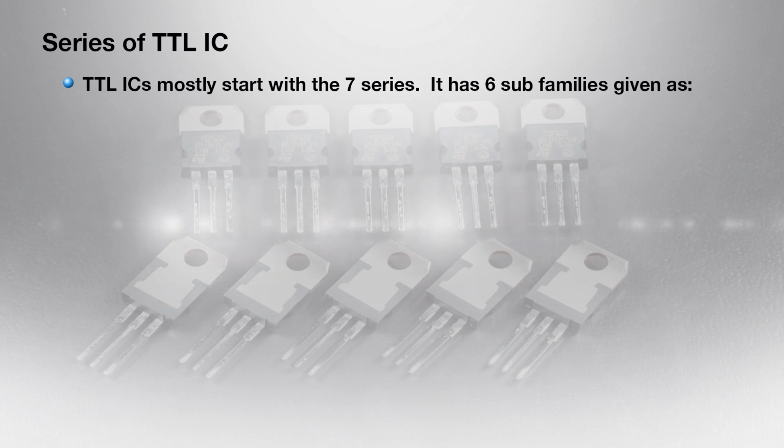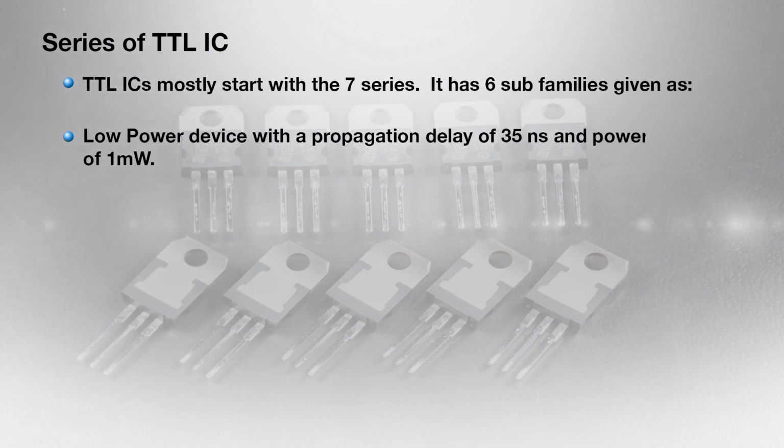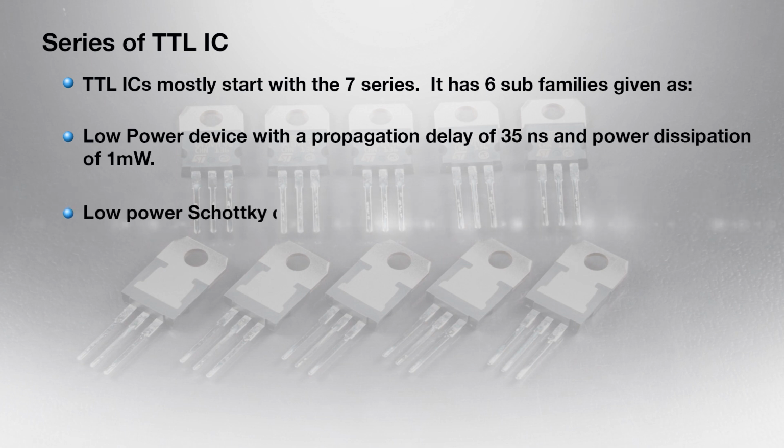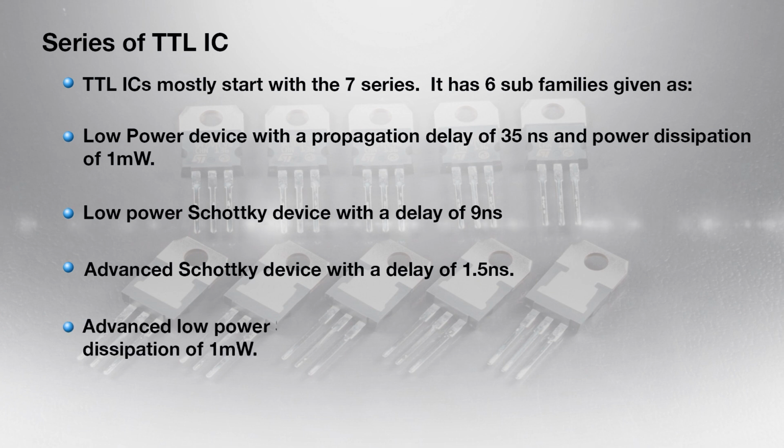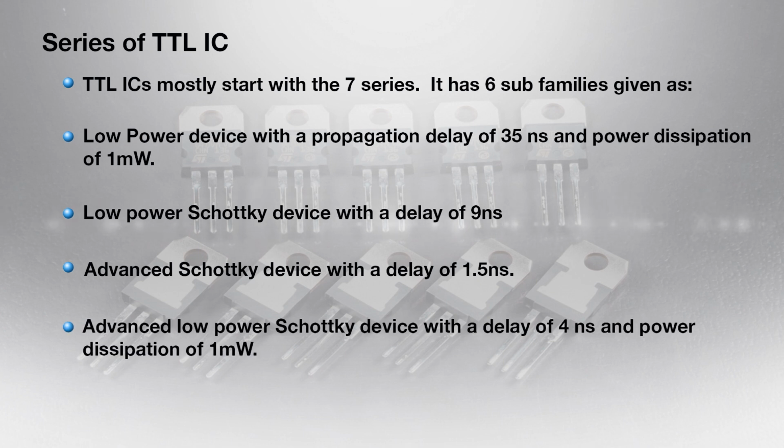It has subfamilies given as low power device with a propagation delay of 35 nanosecond and power dissipation of 1 milliwatt, low power Schottky device with a delay of 9 nanosecond, advanced Schottky device with a delay of 1.5 nanosecond, advanced low power Schottky device with a delay of 4 nanosecond and power dissipation of 1 milliwatt.